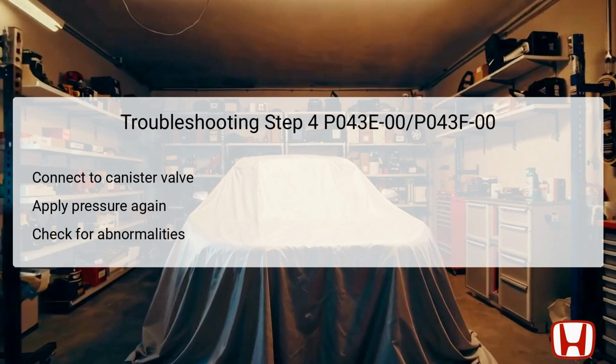Here, pressure is reapplied through the hose, linked to the canister one-way valve, using the same vacuum pump and gauge. By observing the pressure readings once again, you can identify whether the system correctly maintains the pressure. If pressure is not held during this test, it indicates a potential fault within the evap leak check module itself. This result would require further evaluation to confirm the specific component causing the issue, thereby directing the repair process effectively.